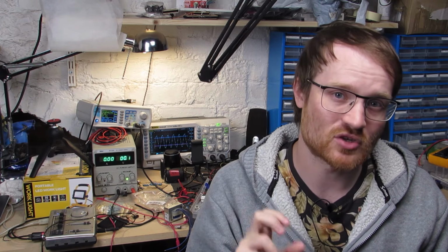So these linear power supplies are great. Low noise, low ripple, super reliable. The only big downsides are excess power dissipation. You know, that to regulate the voltage down, we essentially burn that excess power off as heat. And as we mentioned earlier, the lack of a center tap in our transformer limits the amount of current that we can get out of a similar sized transformer. And as I said, we'll go over that in a future video.